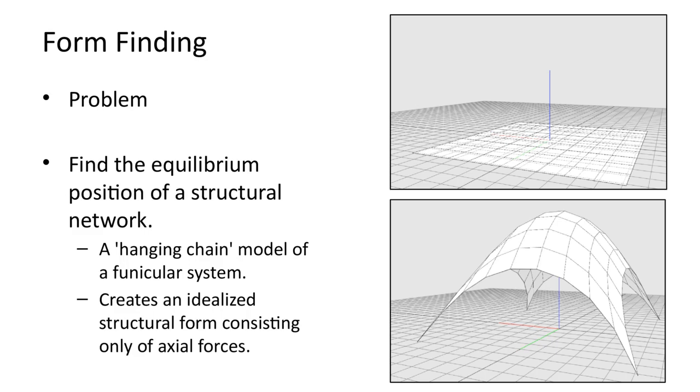In the example, we want to create a catenary dome. The initial state consists of a polygon mesh, lying on the xy plane. Each position in the mesh represents a particle and each edge represents a spring. Note that for polygons with shear edges, only one spring is assumed. The solver then adapts the positions of the particles.